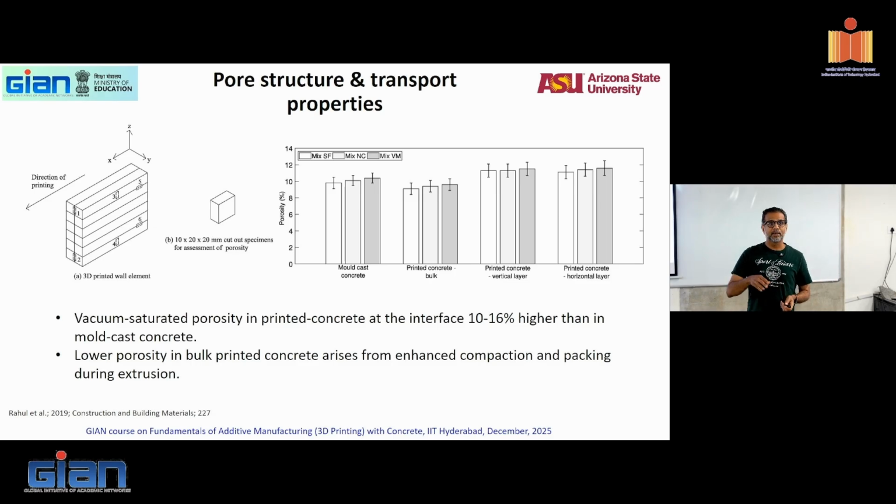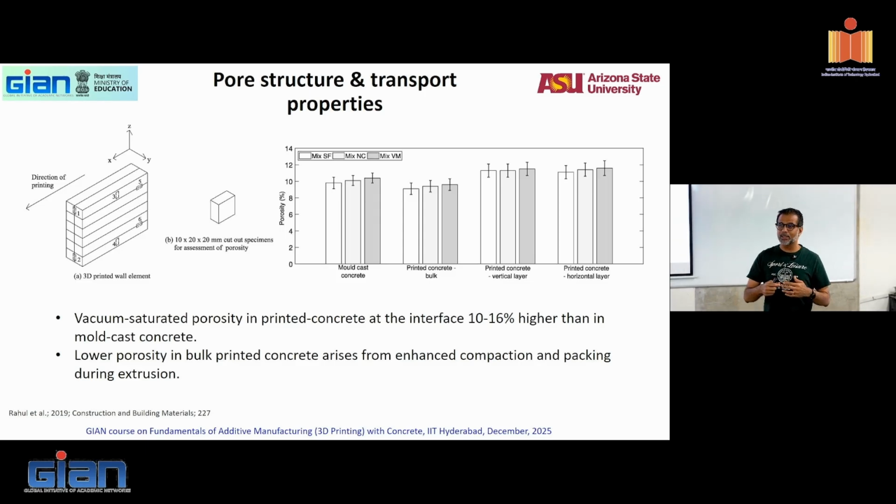Remember the image analysis things that I've been telling you? If you get a very nice microstructure of a material, you can make several different layers and stack them. If you create, like in ImageJ, a three-dimensional microstructure where one phase is pore and one is solid, and stack those microstructures, you can start to quantify numerically the connectivity of pores.